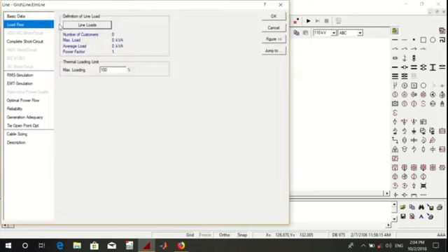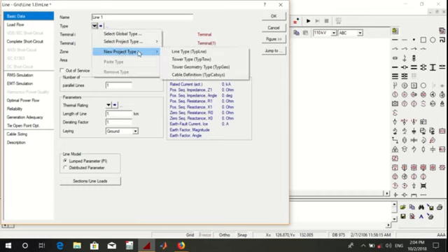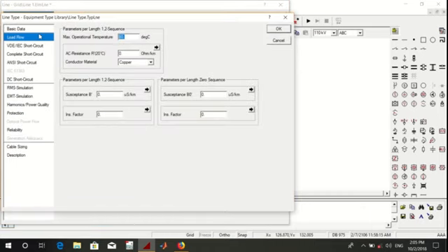Okay. Then the transmission line, define the parameters. This is the name of that line, number 1, I give. Select the type, select the global type, or select a new project type that we want to define for this new line. Then there are required load flow parameters that should be defined. Whenever anyone works in a company, they should know that this transmission line or this cable has a maximum operational temperature of 80 degrees, like these parameters, the type of the material, copper, or you can select any other material. We select copper here, the AC resistance at 20 degrees Celsius, this much per ohm per kilometer.